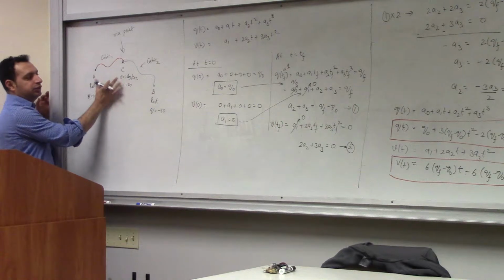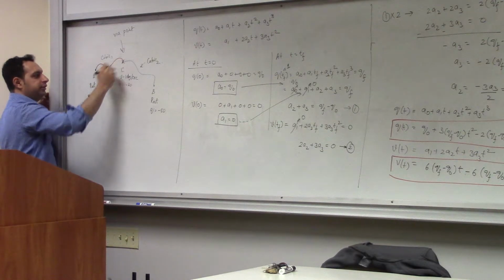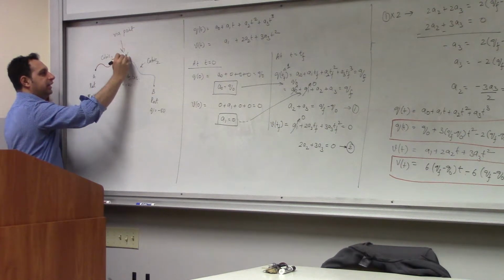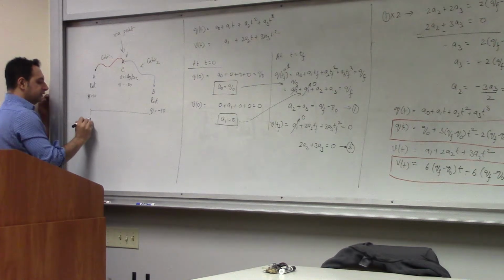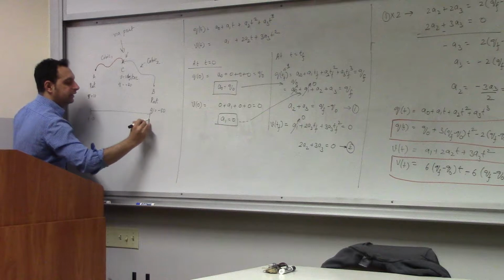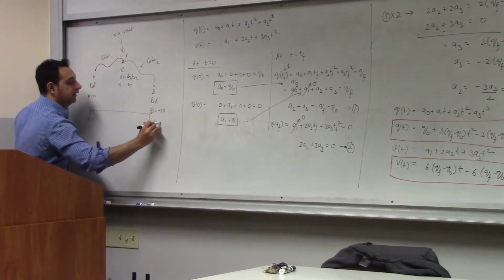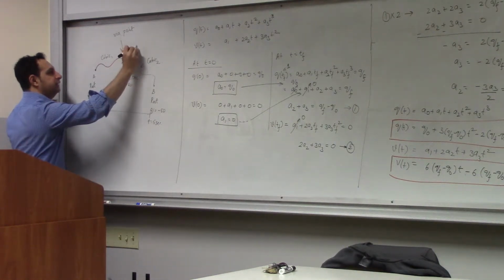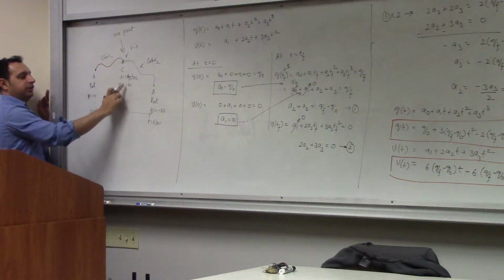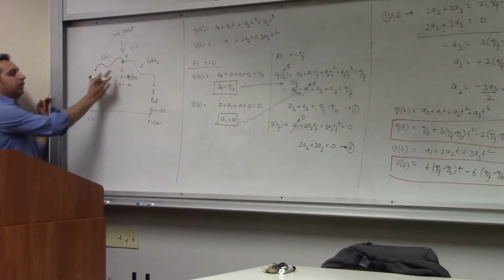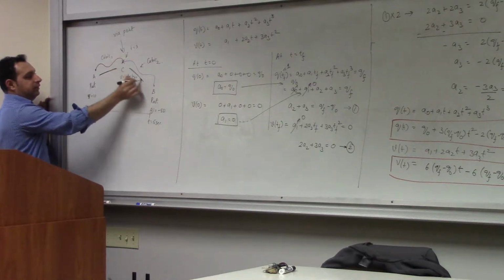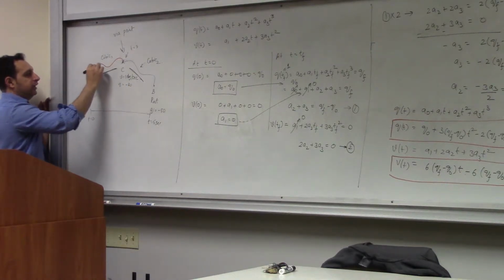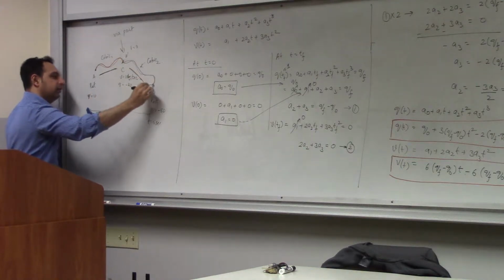This will be one motion, this will be one motion, but it will be continuous. Let's say the whole motion is defined over a timeline: t equals 0, and t equals, let's say, 5 seconds. At t equal to 3 seconds, I want to be at C with this velocity, and this is my joint displacement. So you plan this cubic trajectory as one trajectory, this will be a second trajectory, and then you club the two, so you have continuous motion like that.